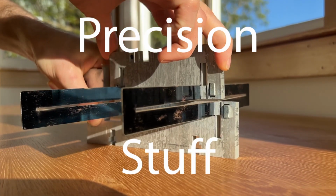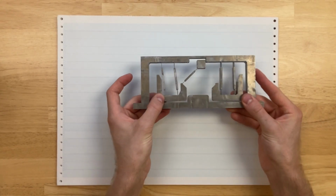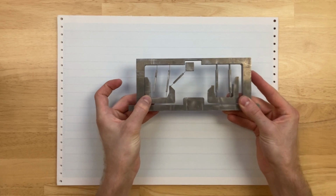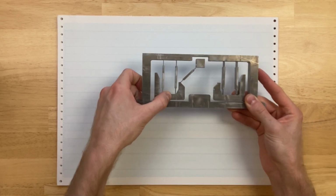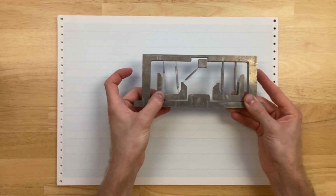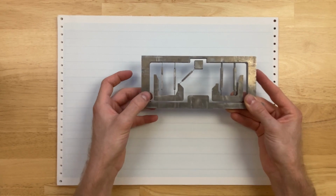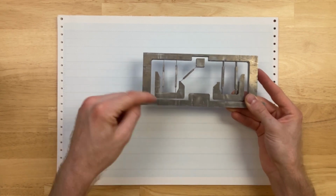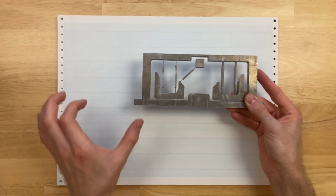Today we're going to talk about parallelogram flexures. This is an example of a parallelogram flexure. It can displace a fairly large amount in one direction fairly freely, but it's actually fairly stiff out of plane. It's essentially a 1 degree of freedom linear motion system with 5 degrees of constraint. However, you can see it has some interesting parasitic properties. As I push it in this direction, the gap at the bottom starts to increase. It's actually not really moving in a straight line, more like a shallow arc.